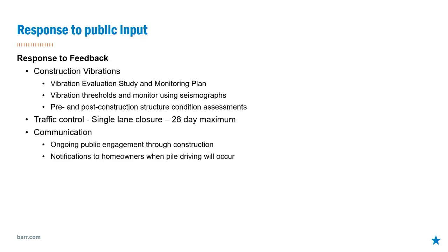Aaron's group is going to do a vibration evaluation study on how we expect the pile driving to create vibrations in this material for this project. And then we're going to set up a monitoring plan for that during construction. We're going to set some thresholds for the contractor to be required to stay under so that we know that we're not going to impact those structures around the site. We're going to monitor the vibrations during construction so we can show that we're staying underneath that and then give the contractor feedback. We're also going to try and make sure that those are feasible thresholds so that the contractor can still complete the work and stay underneath those thresholds.